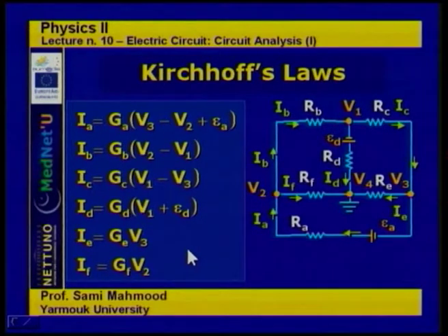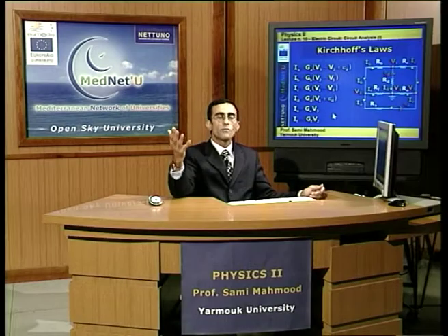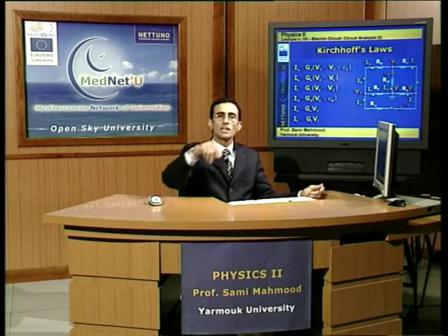So this way, we have only 3 node equations. We solve for the 3 potentials, and from knowledge of the relation between these potentials and the currents in each branch, we can determine the 6 branch currents. This approach shows that we can use a lower number of equations to solve a lower number of unknowns, and then by knowing the relations, we can go ahead and solve the whole problem. So this approach provides us a simpler method.